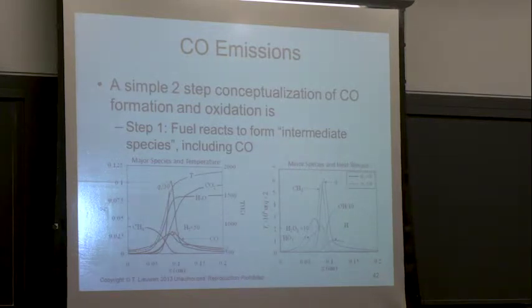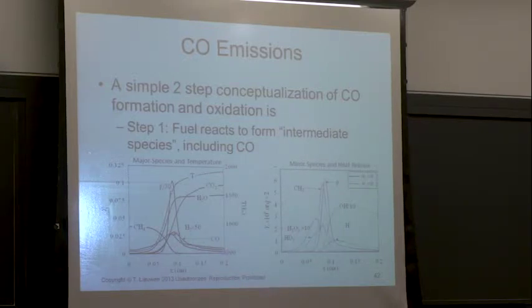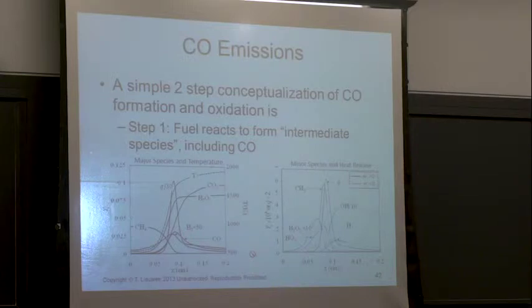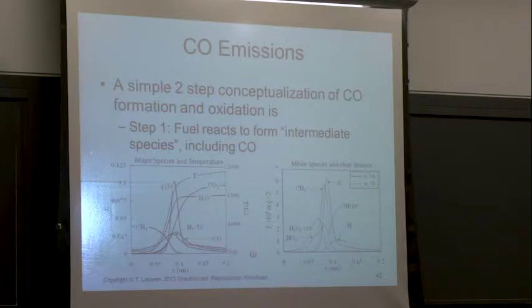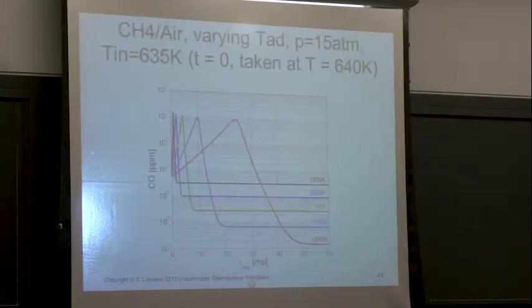But the CO then goes away. As opposed to NOx, which starts at 0 and rises towards equilibrium, CO is falling towards its equilibrium value. So how do you form minimum CO? You give the combustion lots and lots of time for that CO to get towards its equilibrium level. So who can see the conflict? For NO, you want short residence times, because NO is rising towards equilibrium. CO is falling towards equilibrium. So there's this inherent tension, the standard NOx-CO trade-off in systems.